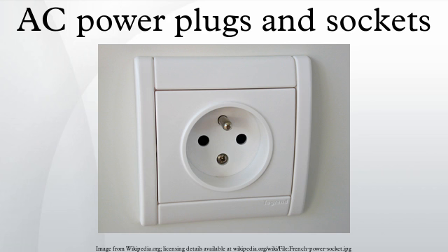Appliance connections and extensions, so that manufacturers need not build, distribute and maintain many similar appliances differing only in the type of plug fitted. A common strategy is to provide an IEC 60320 inlet on the appliance and a detachable power cord to allow connection of the appliance to the socket. The appliance need only be tested to the power inlet. Some types of appliance require the consumer to also change a switch to adapt to different voltages or frequency.